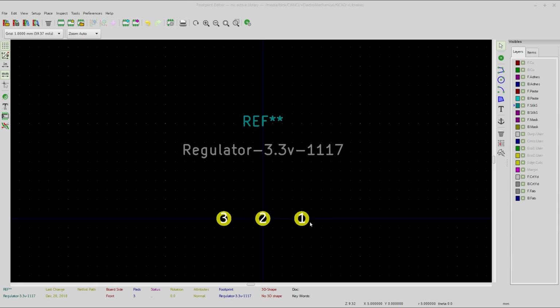You kind of got to make a couple boards, and then you decide how big you want your pads to be. I know there's kind of a standard on all PCBs that you've ever soldered onto. But you might say, I'm not really that good at soldering yet, or this is a tough surface mount component, so I'm going to make it a little bit bigger. Sometimes with the rectangular surface mount components, you can make the rectangle a little bit longer so that it's easier to get the soldering iron on it and let it wick down to the pin.